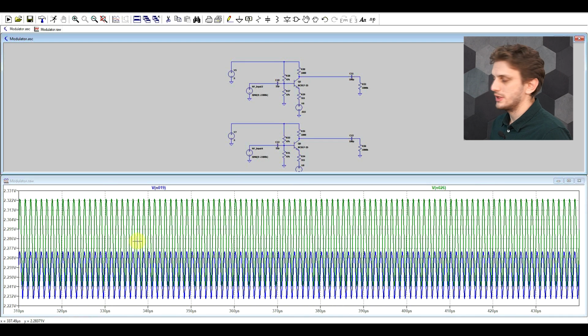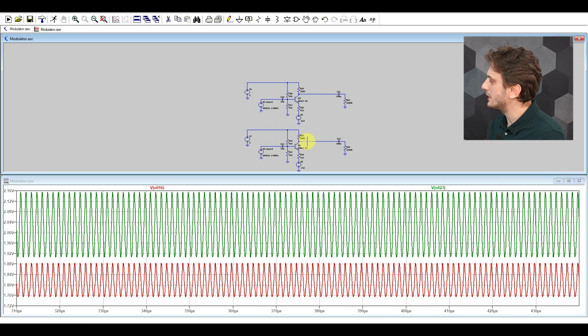So on one side we had 40 millivolts, on the other we had 80. And this is caused by the varying input impedance. So this amplifier has an input impedance between 1 and 2 kilo ohms roughly, caused by the varying voltage between the base and the collector. The end result of this being that we have two completely different amplitudes of signal at the output of the amplifier, even though we have the same input radio frequency signal.